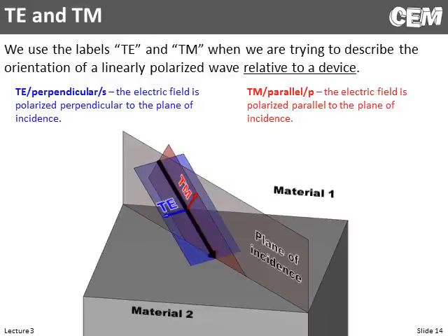Sometimes there's some tricks we can do to analyze them both at the same time with the same model. We can use a circularly polarized wave. So we're actually exciting with both polarizations, and in the end, sometimes we can separate those two answers. So in one simulation, we actually have done two for free, which is why I talked about adding two linears, and it's a little bit easier to understand why you can do that. So does that make sense with TE and TM?